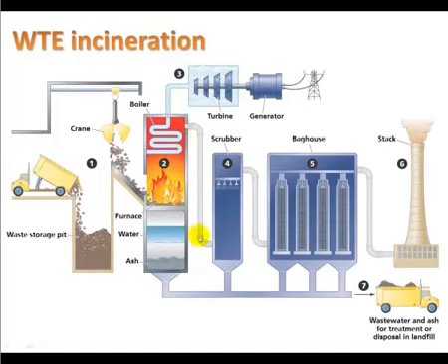And we see these fumes that are coming off in the furnace. They first go through a scrubber, a wet scrubber, which knocks out some of the pollutants, and then from here it goes into a baghouse for particulates. The baghouse is where we can capture particulate matter, so we can capture the ash, and then that ash can go to a landfill, and ultimately whatever has not been collected as ash goes to the stack to be given off as air emissions.